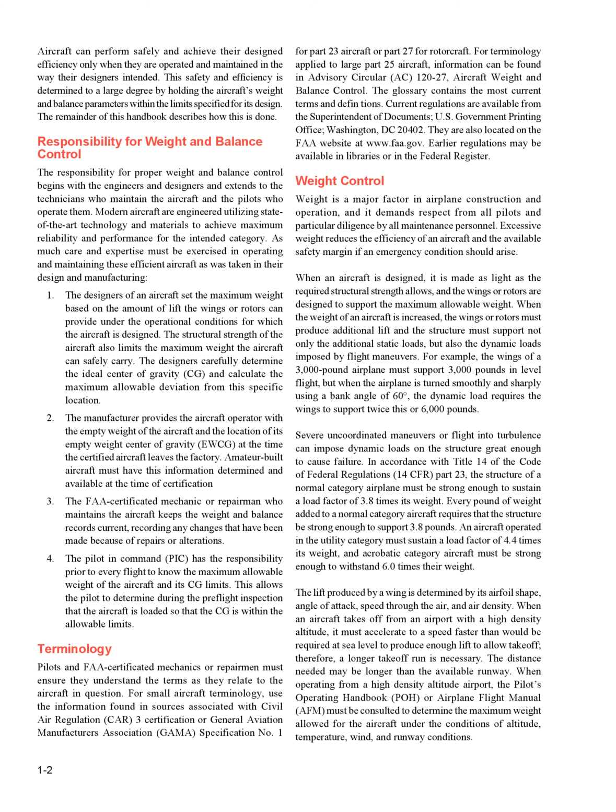Weight control. Weight is a major factor in airplane construction and operation, and it demands respect from all pilots and particular diligence by all maintenance personnel. Excessive weight reduces the efficiency of an aircraft and the available safety margin if an emergency condition should arise. When an aircraft is designed, it is made as light as the required structural strength allows, and the wings or rotors are designed to support the maximum allowable weight.